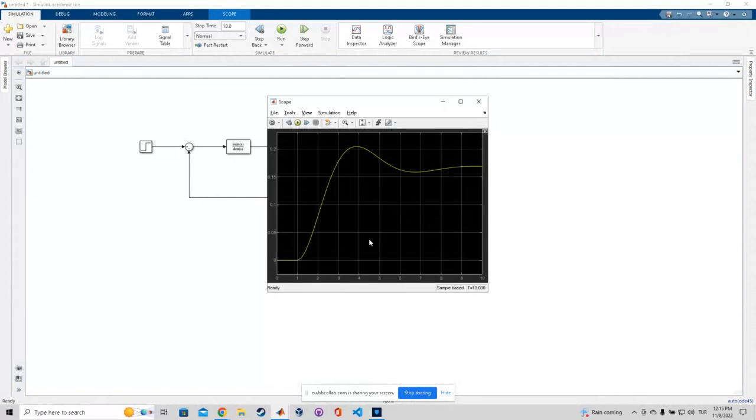All right, you see your system. I ask you to find the settling time. All right, so settling time is this. Look, we have our system, right? System response has a peak, and it has a value between the peak, the maximum values. All right, we have a tolerance of 2% or 5%, and our response value should be between the two tolerance bands. So the time for the system to reach the tolerance band will be our settling time.